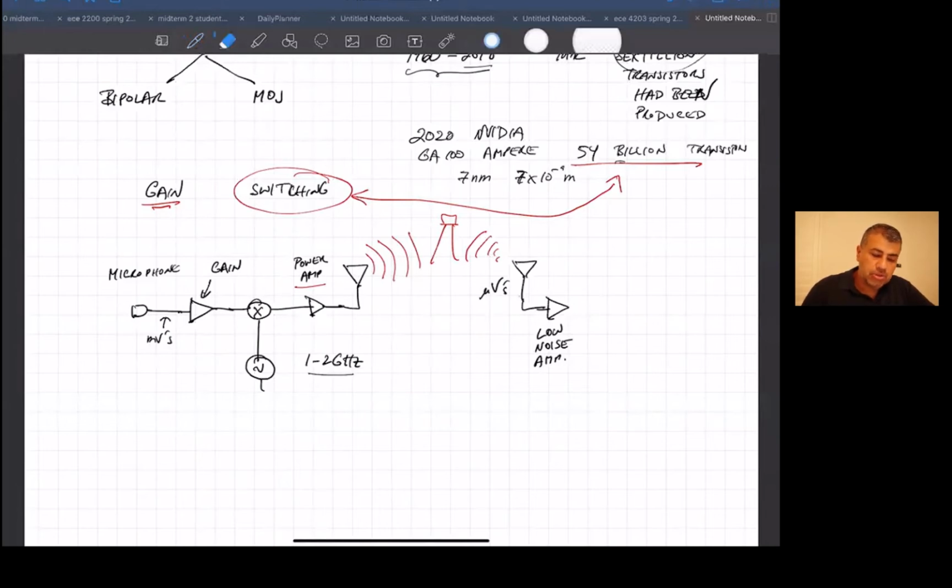And then you need to demodulate that down. So now you do the reverse of what you did before to get it back to the kilohertz range. And then you need some kind of gain amp to drive the low impedance of your speaker or something. So it's just a real cartoon of what this thing might look like.